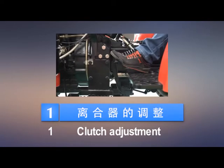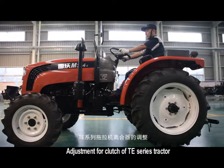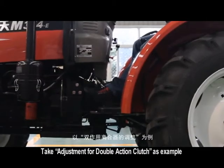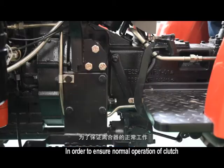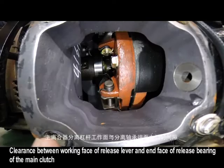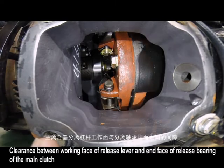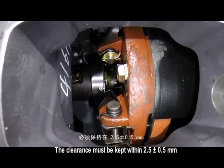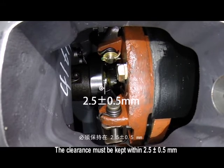One, clutch adjustment. Adjustment for the clutch of T-series tractor. Take adjustment for double action clutch as example. In order to ensure normal operation of the clutch, the clearance between the working face of the release lever and the face of the release bearing of the main clutch must be kept within 2.5 ± 0.5 mm.